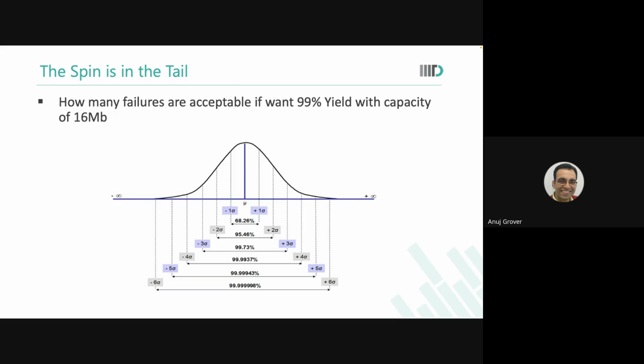In analog design, they typically say that we will launch 1 billion simulations or 1,000 simulations or 10,000 simulations of my PLL to see that this doesn't fail. Now, for memories, you can't do that. It's physically impossible. You cannot have that much compute resource to launch that many SNM and then write margin simulations, and that too not at one voltage but over the entire voltage range. So you have to find a statistical method of analyzing your design. That is why statistics is a very important branch to understand and design robust memories.